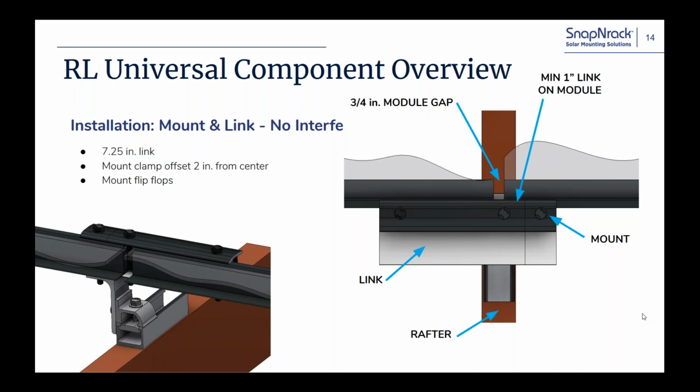And that gets to the whole flash track placement. And I recommend getting all those down. You don't put any mounts in the flash tracks at first, except for that bottom row. So once they get all the flash tracks down on a normal pitch roof, then they come back and install that skirt. On a steep pitch roof, I recommend just putting the skirt in first. And anything above maybe 35, 40 degrees, just throw that skirt down first, and then come back and place all the flashings, flash tracks, and all that stuff.